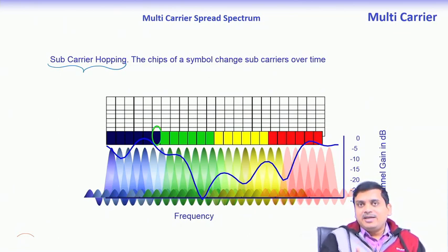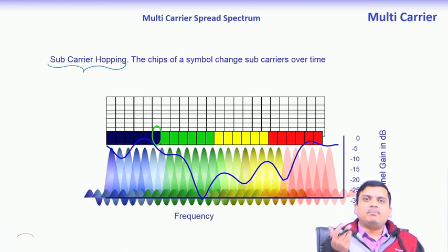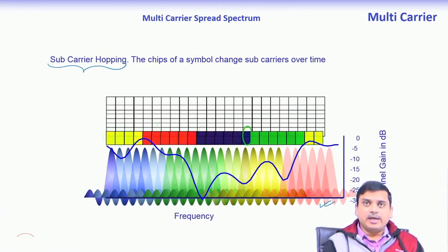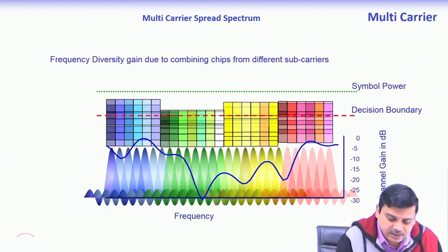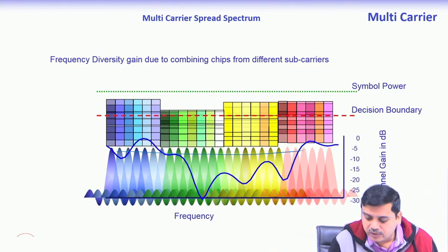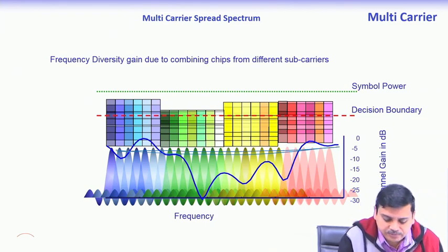So, we are simply taking advantage of the best features which were existing before and combining them with the new features that are given especially through OFDM. So, we are maintaining OFDM, applying those methods on top of OFDM so as to get benefit. If you have the hopping mechanism by which the signals are hopped over different carriers, in that case the combining after averaging over the effect. So, what happens is that each of the signals gets averaged over these different subcarriers.